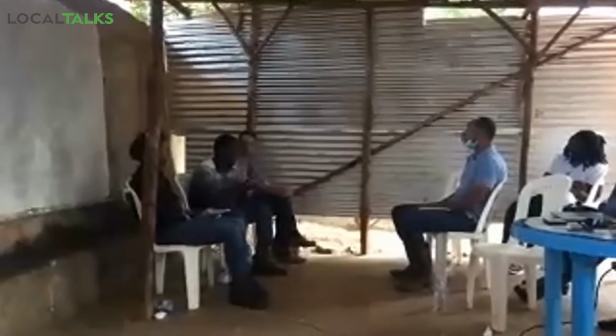Well, I'm going to elaborate on that, because if you don't have the time, our projects are time limited. You're not going to allow for this material to settle before you can finish it. It can even take a year. So you can actually pack and compact a bit, but if the material is not good for you to manually or mechanically compact it, you have to allow enough time for this stuff to settle before you finish it. Otherwise, you'll finish it and you'll struggle with cracks, you'll struggle with a lot of things because the soil is continuing to move. But yeah, it is not as sensitive as other forms of construction in that way, if you have the time.